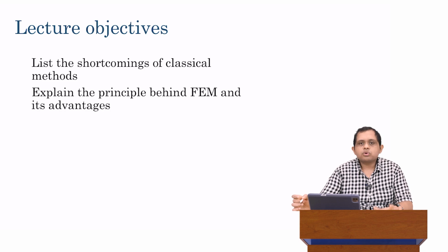So in module 3, we had briefly started by looking at multi-layer pavement systems. The classical theories don't actually analyze multi-layer systems. They analyze slab on grade. But we saw that using certain analytical techniques of the equivalent plate concept, we can combine a series of layers into a single equivalent layer, and then we retrieve an equivalent slab on grade system, which we could solve using Westergaard's theory or any other theory with all the limitations that come with it. And then once we solve for the stresses of that equivalent plate, we can go back and calculate the stresses of the original system.